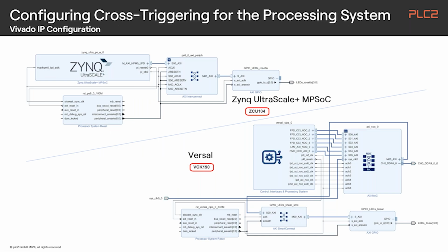Yeah, and here we see a slide where Zynq UltraScale MPSoC is in use. There we have an IP integrator block design with Versal, and this might be a starting point, which has some essential functionality. On the one side, the memory and peripheral capability of the processing system itself. This is also configured with a CIPS module in Versal, and then some services in the programmable logic.